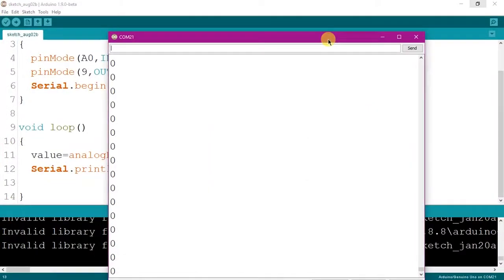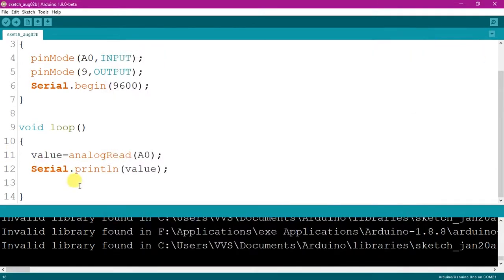We can do a program by combining the previous video and today's video. So let's do it. First we need the analog input as we acquired. Now I am going to write the value using analogWrite to the 9th pin. While using analogWrite, we cannot give HIGH or LOW. We must specify the value to be written. So the analogWrite value varies from 0 to 255 only.